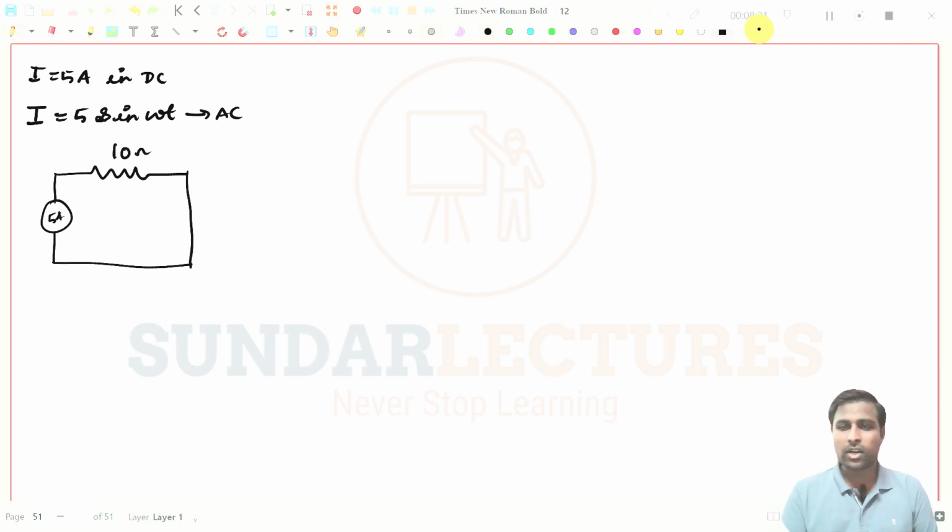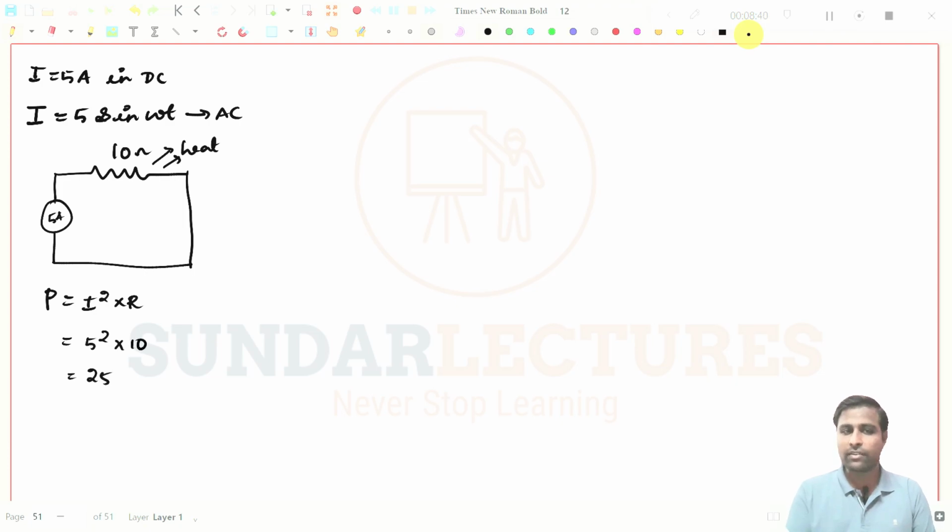And what is the power loss? Which means this resistor will dissipate heat, right? That is what we have learnt in the DC circuits. So what is that value? P is equal to I square into R, right? So what is I square here? I is 5 square, that is 25 into 10, right? So 25 into 10 will give you what? P is equal to 250 watts.